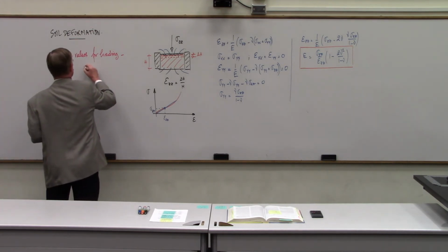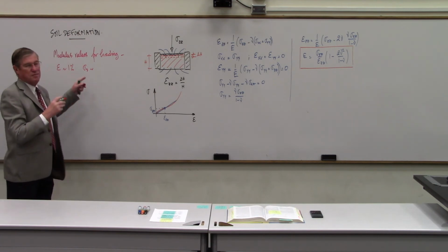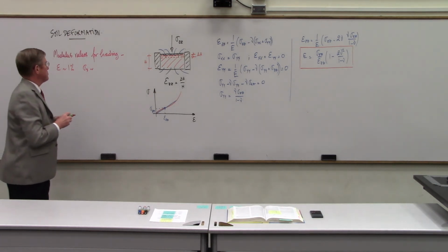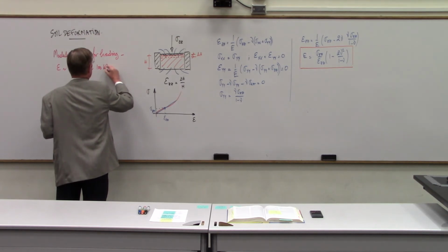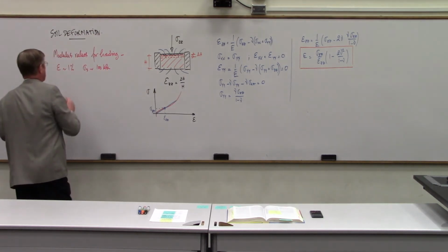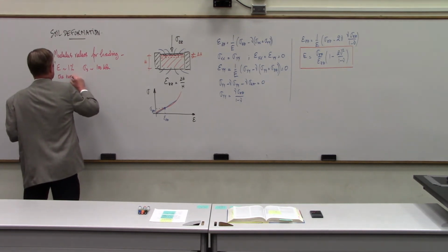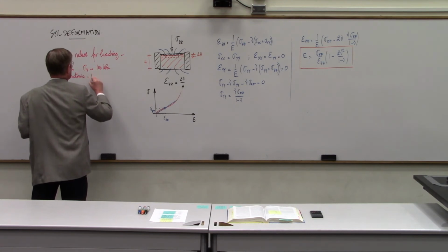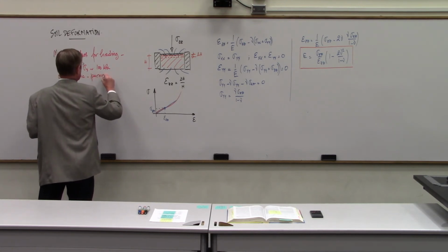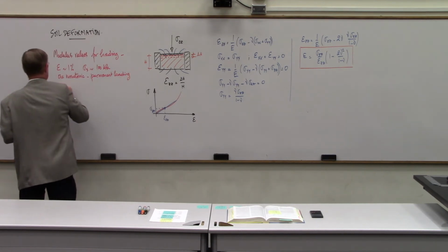Stress level: I'm talking about foundation engineering basically, so maybe 100 kPa. Rate effect, 1, monotonic loading, and then permanent loading. So there are no cycles or rate effect.